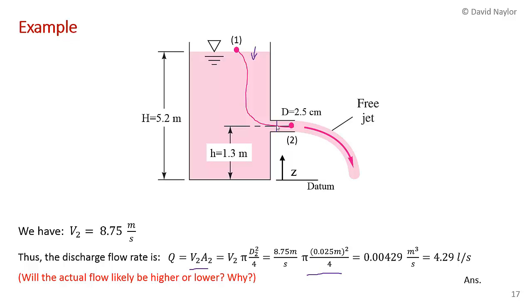You actually have a velocity profile across here, and it sticks at the surface. So there's some drag. This pipe would exert some drag on the flow because of the no-slip condition. So you're going to get a slightly lower velocity. Also, there'd be these sharp edges here, and we'll learn about that later on.